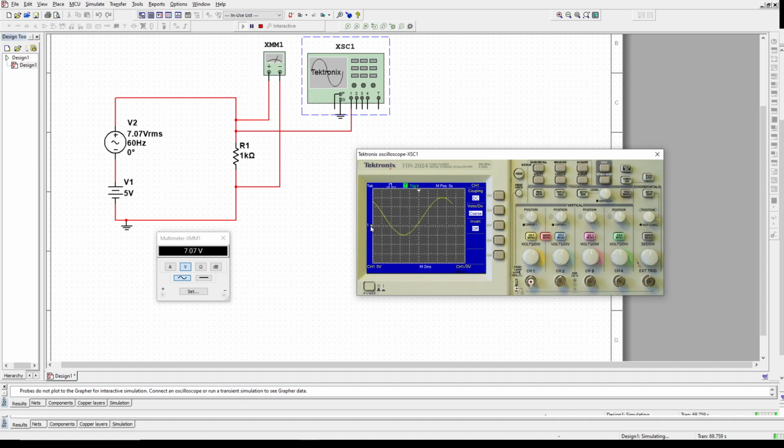Okay. Now, we see this thing is not equally displaced between the ground line on top as well as on the bottom. Looks like the whole waveform is raised a little bit. Well, let's see if we can ignore the DC part of it by selecting the coupling. And that basically comes up if we call up the channel 1 menu. So we're coupling DC, and this is a toggle button. So let's toggle that. Oh, here's AC.